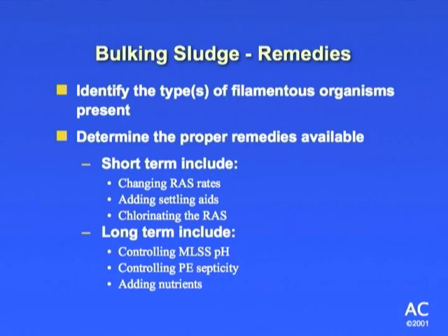Oftentimes you may enlist the help of experts that do this all the time. This guy out in California, Jenkins, people send their sludge samples and scum samples out to his people, and they'll do staining and microscopic analysis, and they will actually identify the specific problem organism that's causing the trouble, and even come up with remedies from their database, and also what could be causing it. They'll tell you, here's what we think typically causes this to show up, and here's typical remedies that have worked across the country. So they've got a huge database. That's a resource that we've used before.